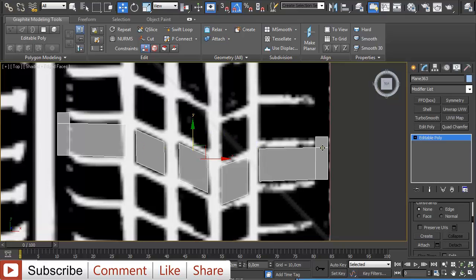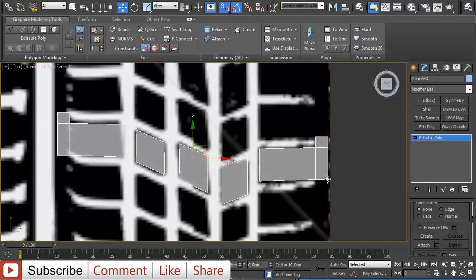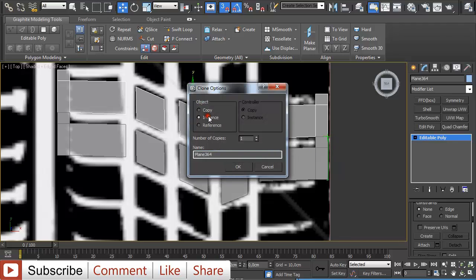And just duplicate them by turning the snap tool on and hovering over this edge until the mouse cursor turns into these four-sided arrows, holding shift, and just move it up until it snaps to the upper side.